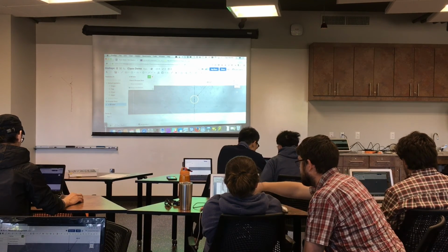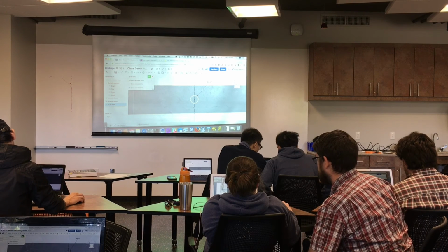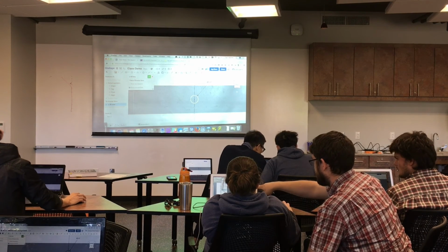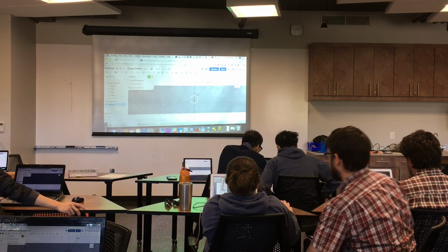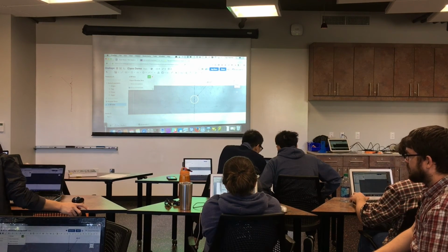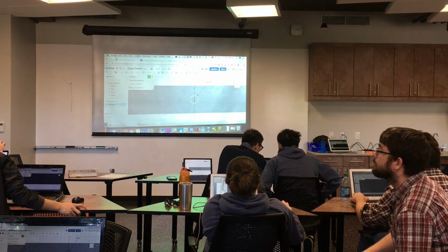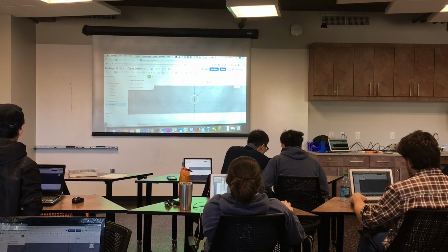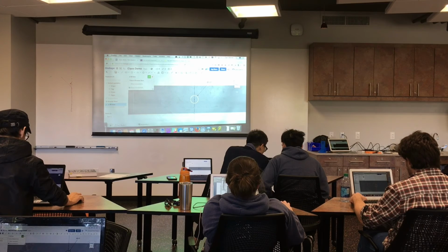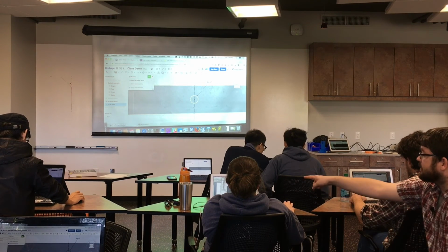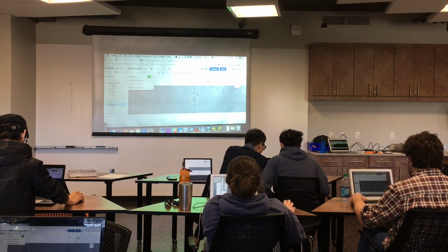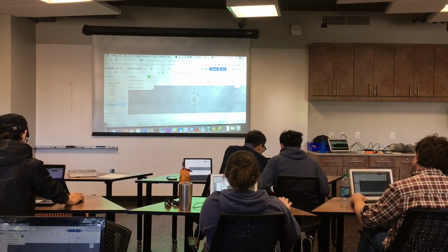Okay, so now draw another line from the center to the top, or top to the center, however you want to do it. And now double click where you ended to end drawing the line. Yeah, there you go. And now hit escape so you have your pointer back, and then you can select both. Oh, scroll wheel. Hit the equal constraint. Yep. Does everybody have this centered hole?